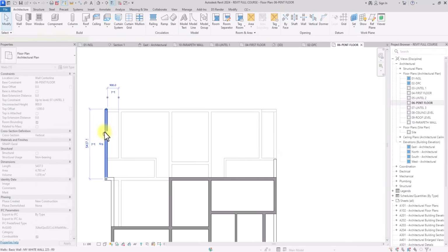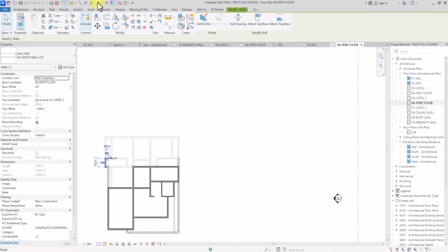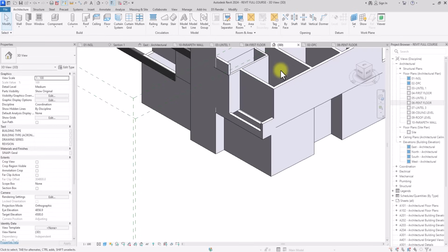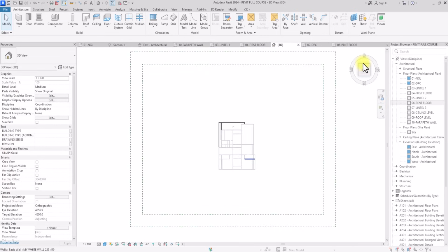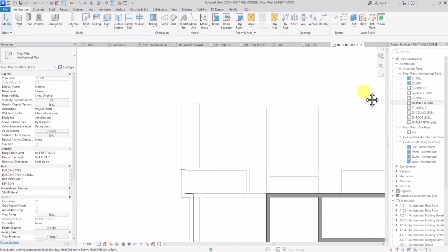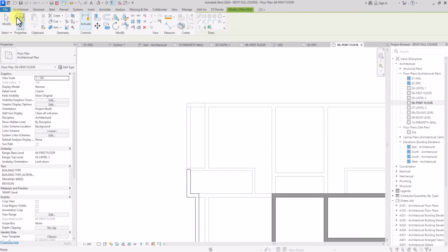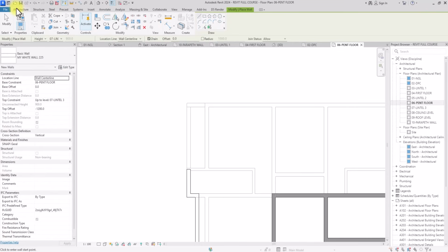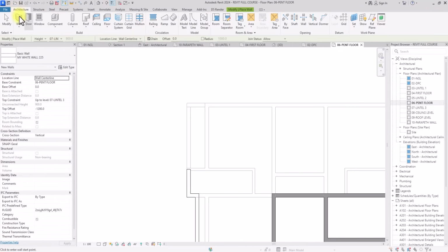But before doing that, if you remember, there are balconies here. So I want to also do some balcony work here just to make sure that it fits in the character. So what do I mean by that? I'm just going to go back to this paint floor and I'm just going to draw a wall. I'm going to draw a wall from the lintel beam, indicating how the beams will drop down over this balcony. So I'm going to go to walls.